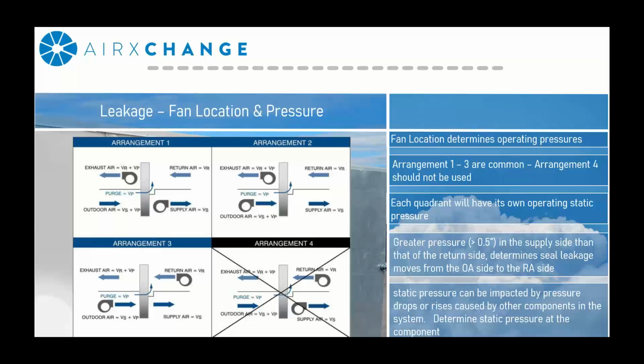And once again, when you're looking at these fan arrangements, you want to take into effect the entire system. That's because the fan operating pressures are not only affected by the energy recovery component, but also by coils, filters, louvers, or anything else in the system that could add static pressure, which would affect how the wheel operates, or I should say the component operates.